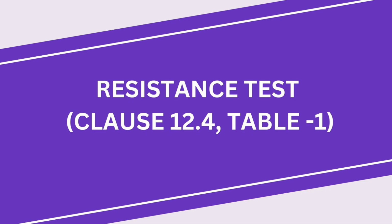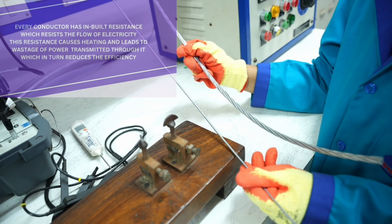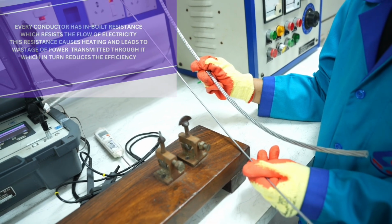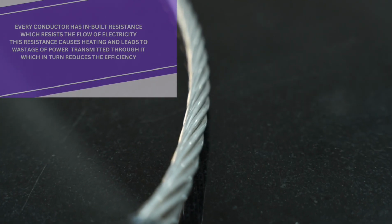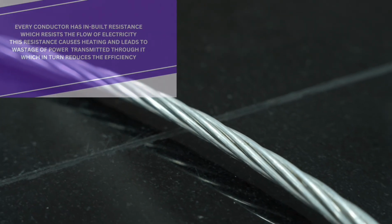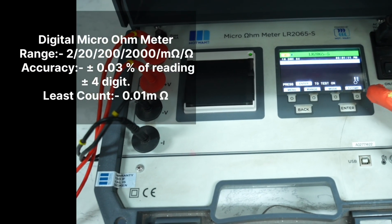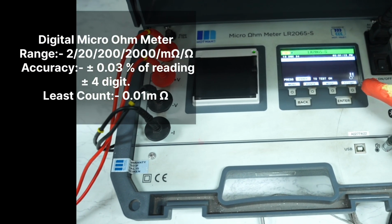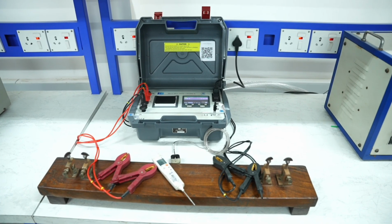The next test being demonstrated is resistance test. Every conductor has inbuilt resistance which resists the flow of electricity. This resistance causes heating and leads to wastage of power transmitted through it, which in turn reduces the efficiency. The equipment used for this test are digital micro ohm meter, thermometer, test bench with terminals and clamps.